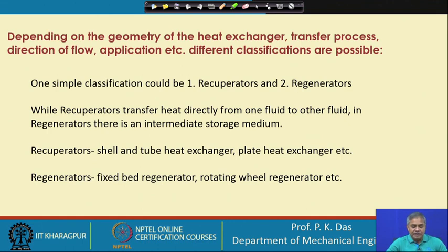Then regenerators: there is an intermediate medium which will temporarily store thermal energy. So, this is a kind of storage type heat exchanger, and there is a third medium in between the two fluid streams. They are also very important, though they are not as many in number as recuperators. So, fixed bed regenerators, rotating bed regenerators, and there are other examples we will find as we proceed with the course. So, these are regenerators.